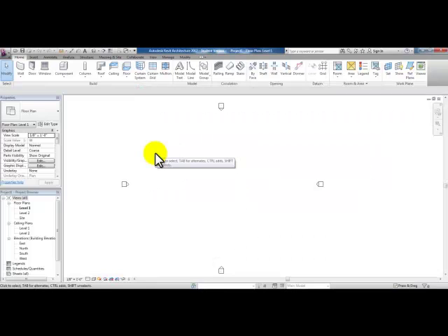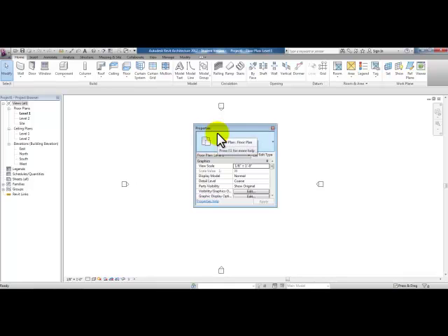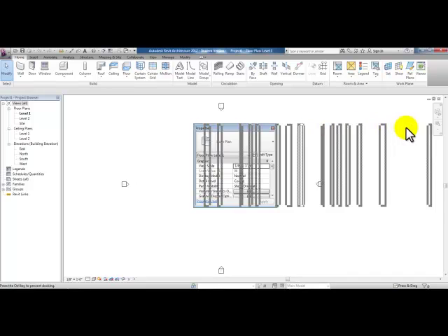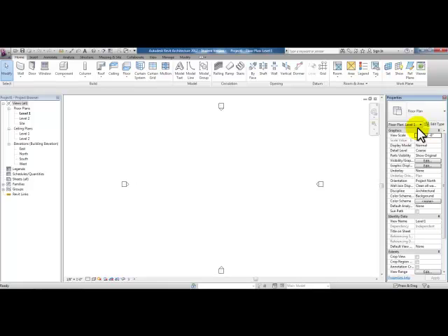When you first download Revit, the Properties palette is on the left-hand side. You have a Properties palette and you have a Project Browser. You can hold your left mouse button down on this bluish-gray strip next to the word Properties and drag that Properties palette out into the working area, and then continue to pull it to the right hand side until it changes its shape. Let go so that you can dock it on the right hand side. This way you can see all of what's in the project browser on the left hand side and all of what's in the properties on the right hand side.